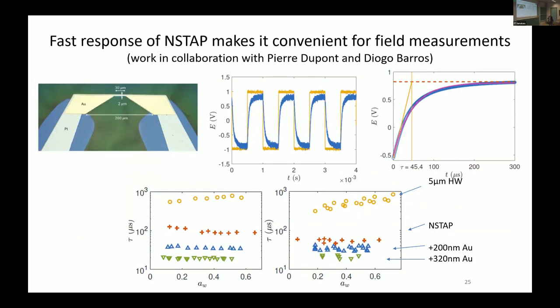And one thing that we basically just exposed it to step waves like this, with a nice constant current. It's a nice first order system. We can fit the first order curve here. And what we thought was that, well, you have a small wire here. There will be some heating here as well. So what if we reduce the heating by putting gold on here? So we reduce the resistivity of the holders, so we get more of the heating localized to the sensor.